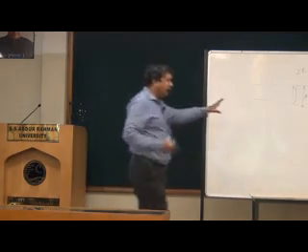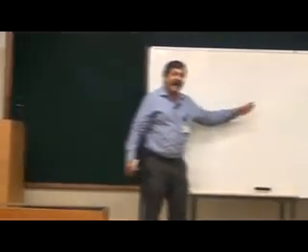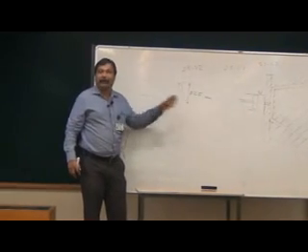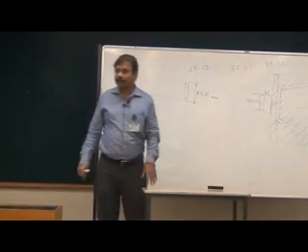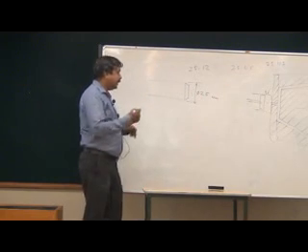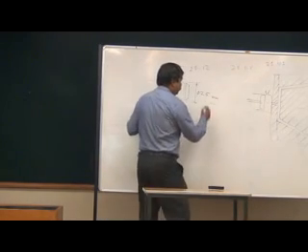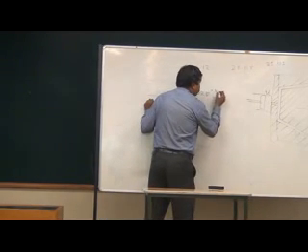So when I design a component and say the diameter is just 25 mm, my design is incomplete. I should say the diameter must be plus 0.05 minus 0.08.